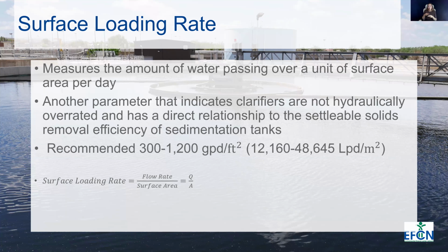It is recommended that you have a surface loading rate of between 300 and 1,200 gallons per day per square foot. Now, you'll notice that unit's a little different than our previous problem where we had feet and we talked about linear feet. This is square feet because we're talking about our surface loading rate.